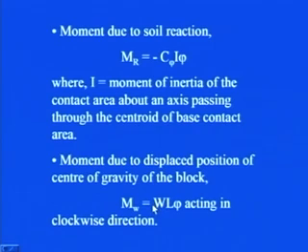That is why we are putting it with a positive sign here. However, the soil reaction we put with a negative sign, which means that it was acting in the anti-clockwise direction. As you saw, in the case of translation we were taking the equilibrium of forces. However, here, since we are subjecting this system to rotation about the y axis, we will be taking the moment equilibrium, and that is how we find the different moments which will be there when this is subjected to rotation about the y axis.